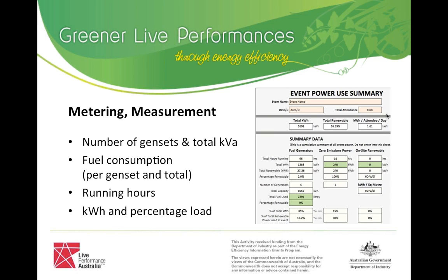Okay, so if you're in a situation where you've hired 10 generators and the local fueling company is going to come and refill the gensets every day, and they're not really going to be completely full, and you don't know whether you've emptied them out or whatever, obviously you're going to be able to get a total fuel invoice from the fuel provider. So that's one way that you can do it. You're not going to be able to get the specific fuel consumption for each generator, so you don't get down into that detail that you want. So that's when kilowatt hour logging, I think, is going to be quite important.